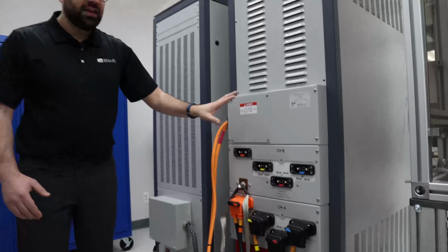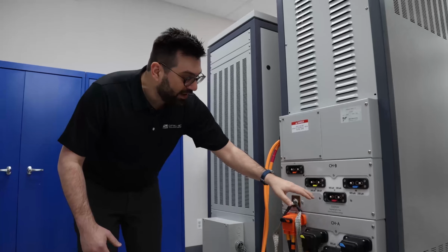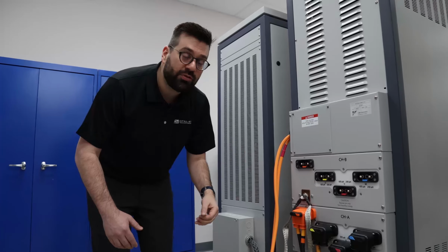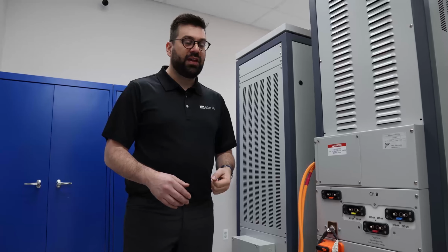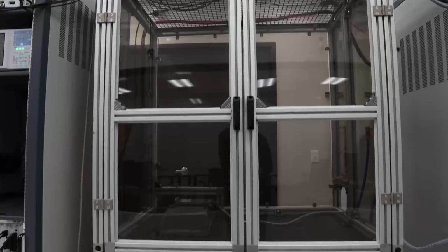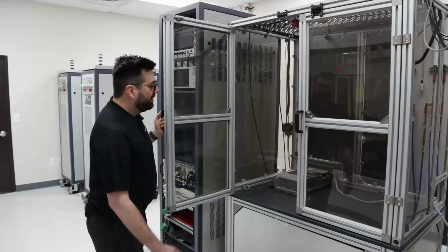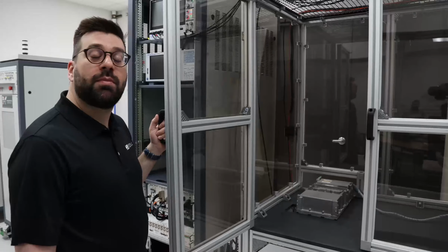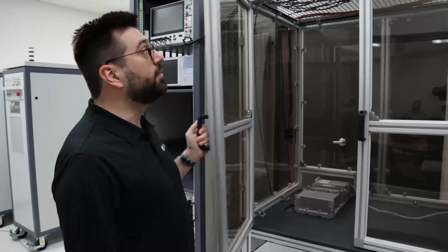Keep in mind that we have the line inductance in this equipment as well. We offer at first the 105 microhenry or 210 microhenry options. If something differs for your application, that could be changed as well. Now let's go to the inverters. So now we are in front of the inverter cabinet. If we open that, we have here a Semikron generic inverter for a 3-phase PMSM machine. This will be the inverter that we'll use today during the demo.